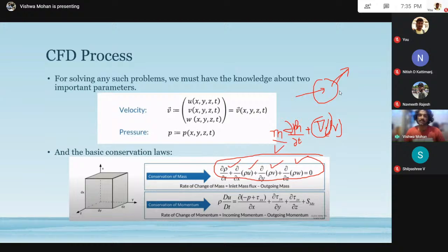And this constitutes the mass conservation, or something that people call the continuity equation, which is different, right? We'll talk about it. So momentum conservation again. Another new term is this capital D. This is called the total derivative, which takes care of the fact that the variable it is operating on is studied both with space and time. So change in U with space and time is studied with the help of this.